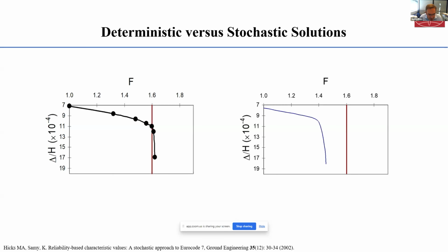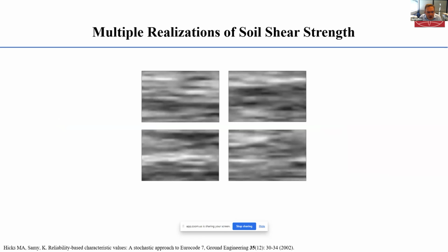However, what you've got to remember is that when we carry out an analysis like this, we are making numerical predictions of the spatial variability for the slope. And for a given set of statistics, for a given mean, a given standard deviation, and a given scale of fluctuation, we could come up with lots of different predictions of what the spatial variability will look like for the slope.